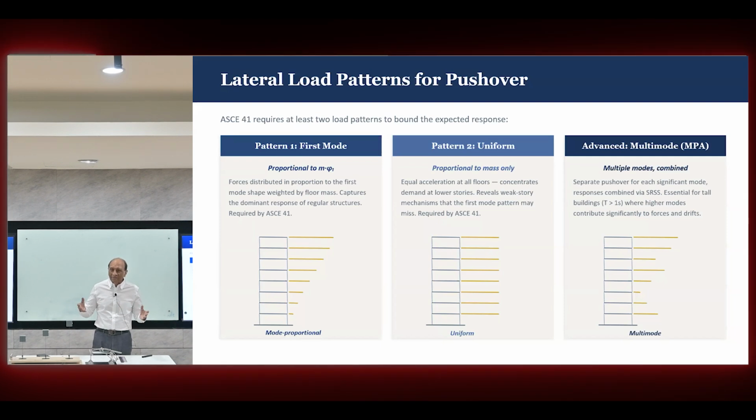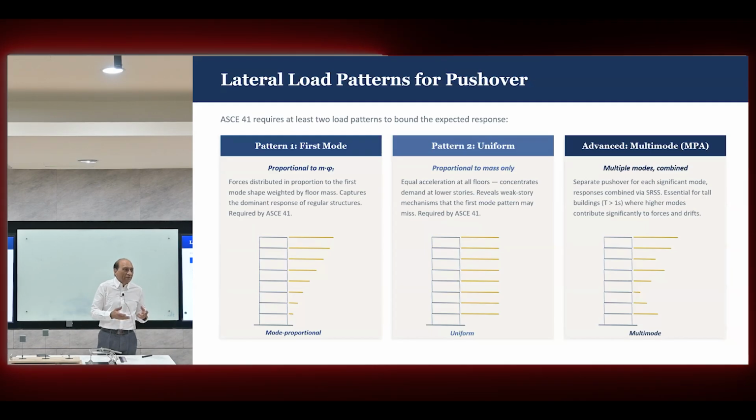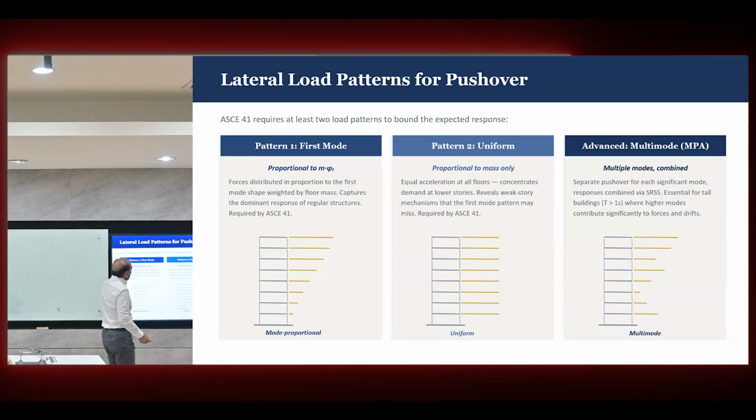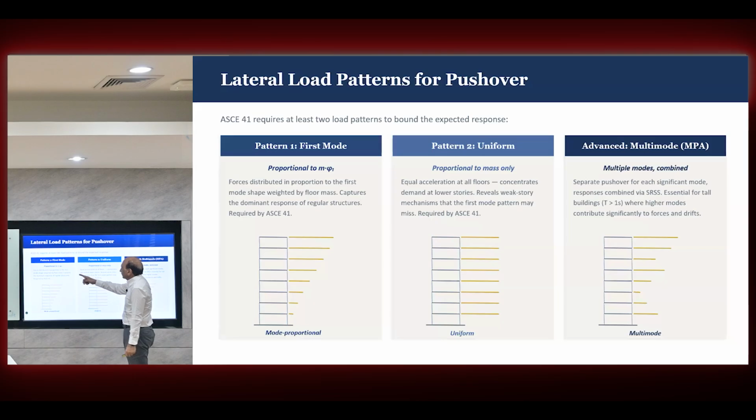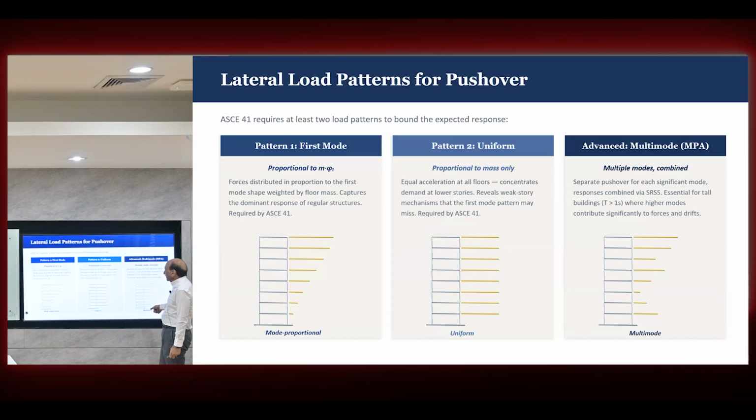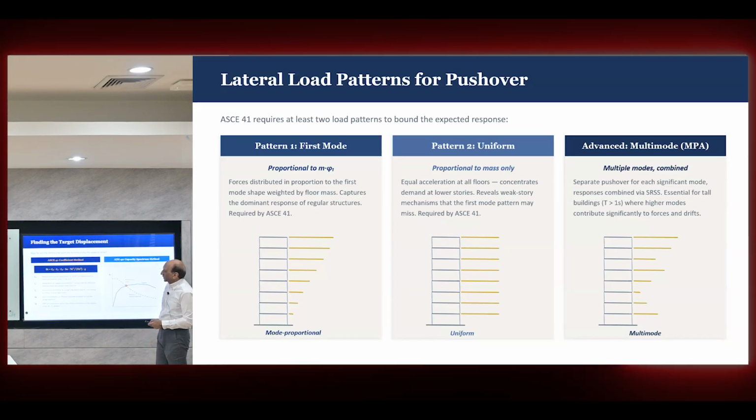At one point, the most research was done in pushover, and so many methods came up. Now it's gone back again, and only 2, 3 have survived. So basically, you do that proportional to mass only, proportional to the modal deformation, and this is for multimodes. So those are the 3 patterns that you can specify.